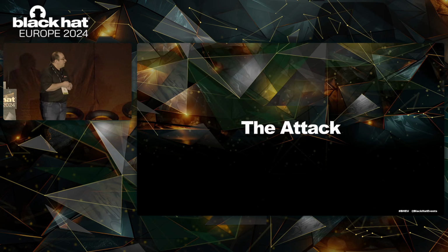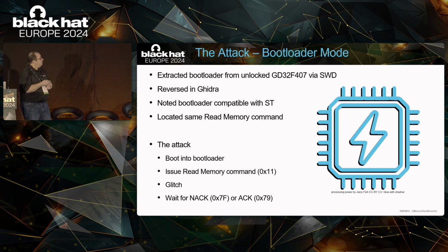So let's talk about the attack. From prior research, we suspected that the GigaDevice's device was susceptible to being attacked in bootloader mode because the STMicro showed that it could be. So we extracted the bootloader code from the device, reversed it in Ghidra, and then verified that the command set in the bootloader matched the STMicro. So the same read memory command existed and operated in the same way.